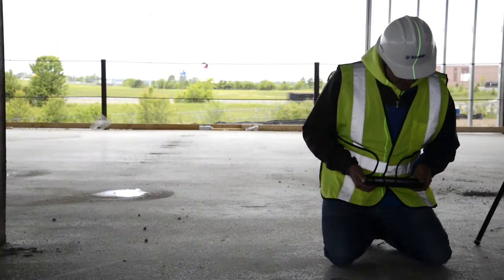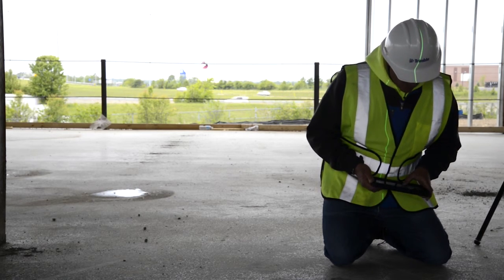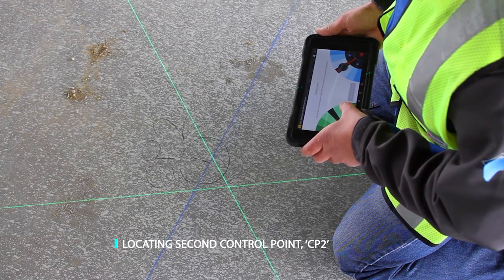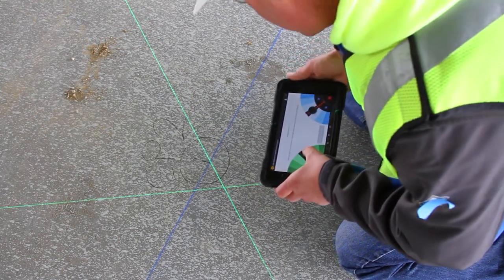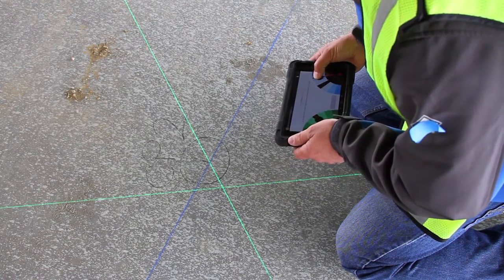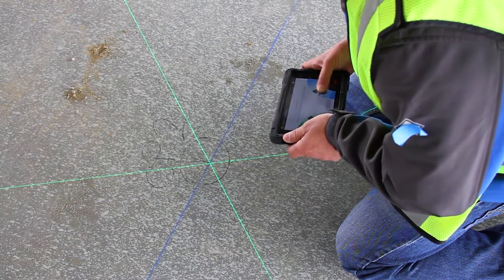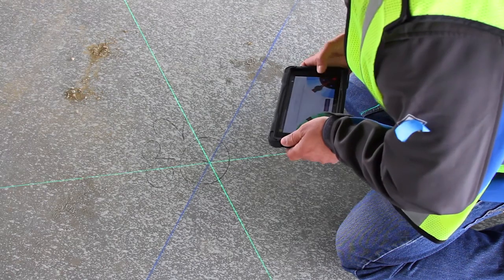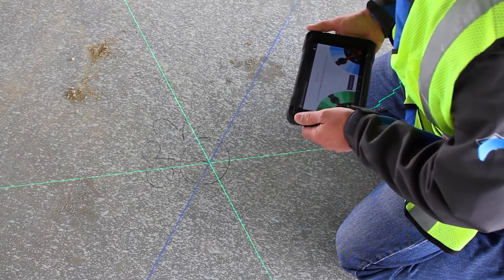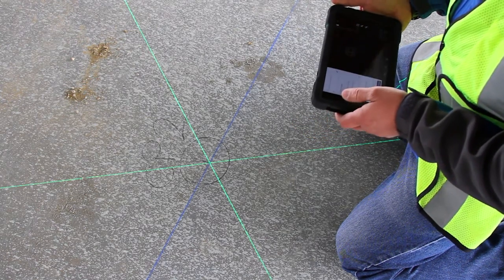So now we're going to our second control point. We want to make sure that we're really being careful when we're picking up these control points. So do your best to position the lasers exactly over the point. Once you've got the second control point located, now you can move on to verify setup.